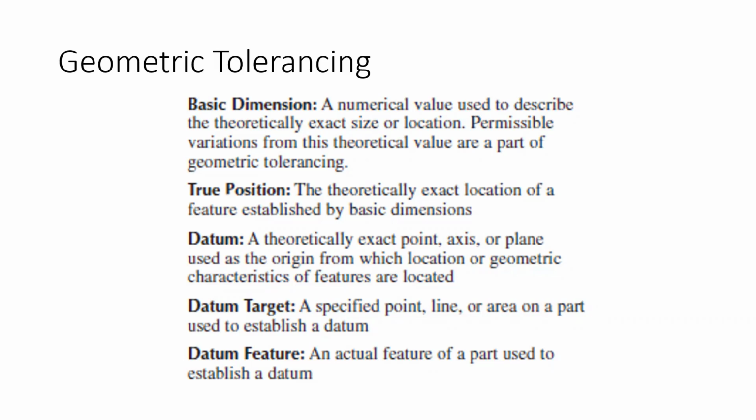So that variation is part of this geometric dimensioning and tolerances. And a lot of times these basic dimensions, I don't want you to think of them as like all the dimensions that we've been doing thus far are basic, but this has to do a lot with positional tolerance dimensions. They're basic. You'll see these with a rectangle around the number. So it'll be a regular dimension like you've seen, but the number will have a rectangle around it. So that's going to be a basic dimension.